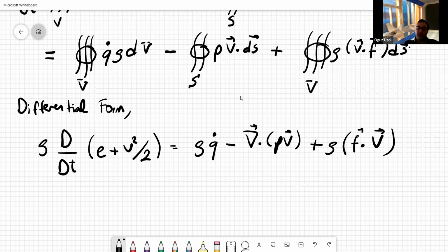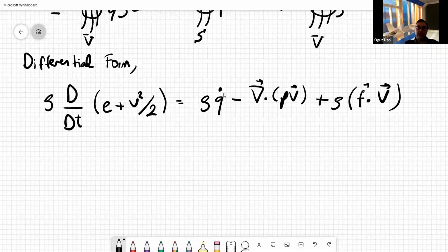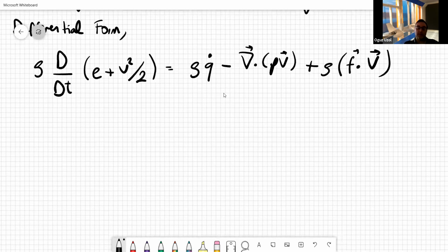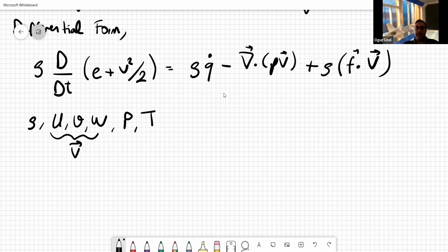No, as we discussed yesterday, we actually have 6 unknowns, because let's remember what those were. So first of all, density, it's a compressible flow, as we discussed. We have to solve for density, and velocity components, let's say U, V, W, and pressure and temperature. So these are velocity components. So that makes 6 unknowns that need to be solved. And so far we had 5 equations.